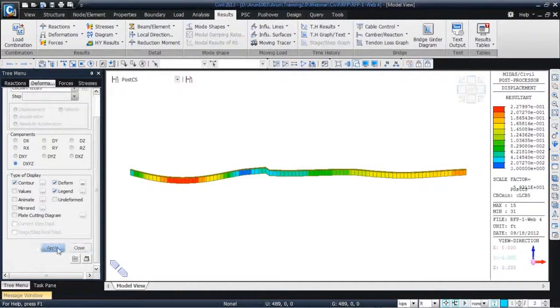And you can see the value has sharply decreased with tendon property 4, which is 2.27 now. So you can see with increasing tendon area, the deflection is decreasing. But now the question is to optimize it. So what I'll do in the same model,